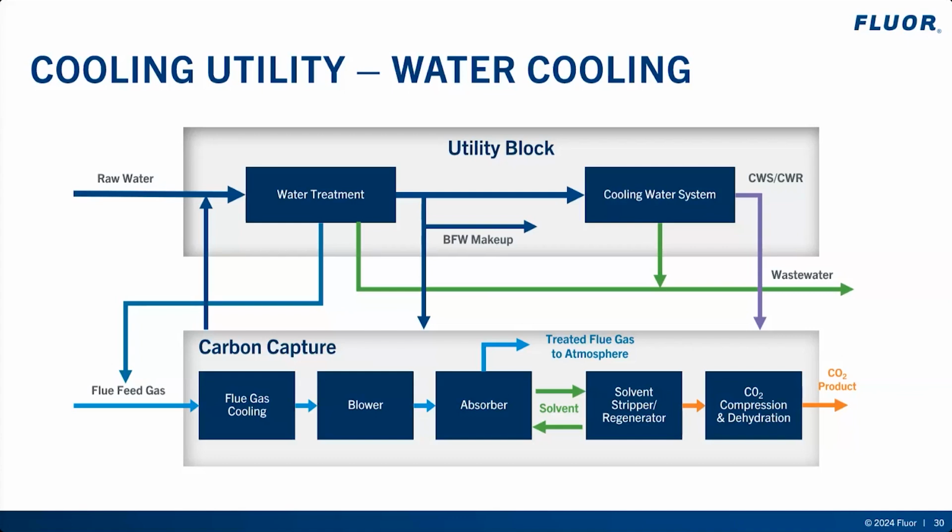These factors can affect both the technical and economic feasibility of an expanded water cooling system. The benefits of water cooling should not be overlooked, but projects are best positioned to start this assessment with an understanding of the water constraints of the facility being evaluated. Often, a hybrid solution consisting of both water cooling and air cooling provides the most feasible option.